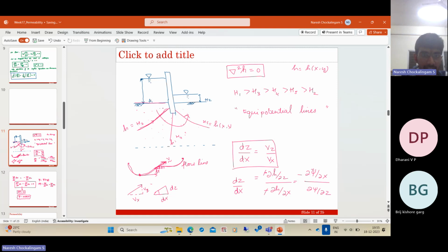Physically, it means that you take a manometer, a tube, take a point in soil and plug it in, and find out to what height the water rises there. That varies at every point in the soil. Therefore, this height to which water rises at every point in soil is a function of x and z.